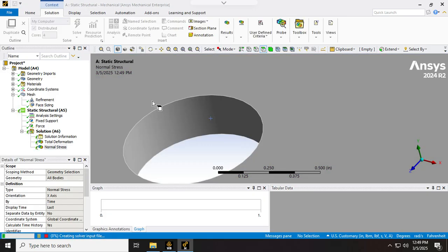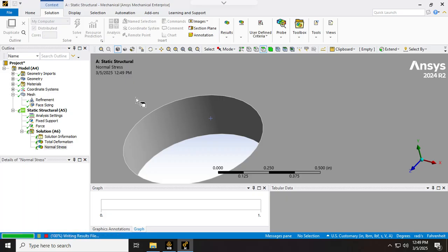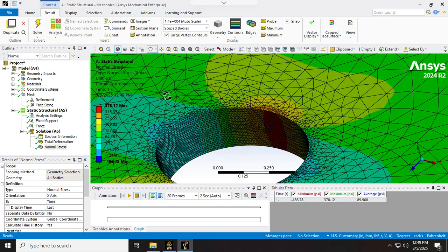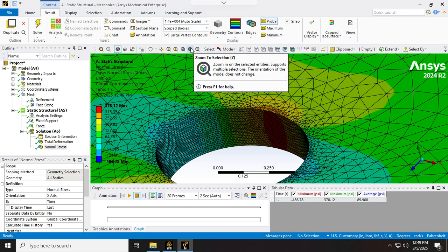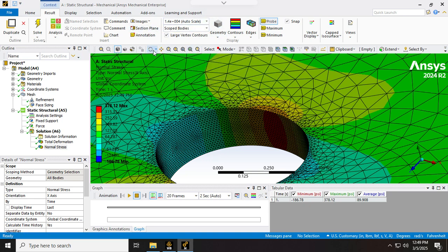This is called convergence analysis. We keep doing this until we see that the results converge to a certain number. You see it's a lot finer right now. Look, the result is no more, see, only the third significant figure is changing. It's far more consistent, so we can stop here. You can also move to the other side.